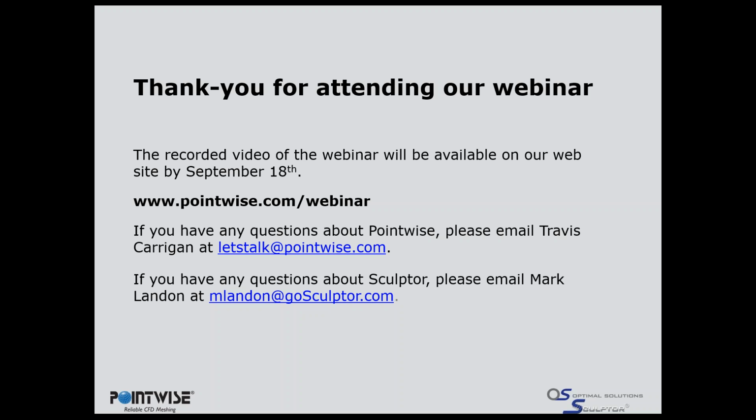One question was if this was RANS or LES. This was a RANS calculation. And then another question was maybe you could reiterate what the 4 control parameters were for this optimization. Well, we grouped the control points near the windshield so that we controlled the rake or the angle of the windshield with respect to where it meets the hood.